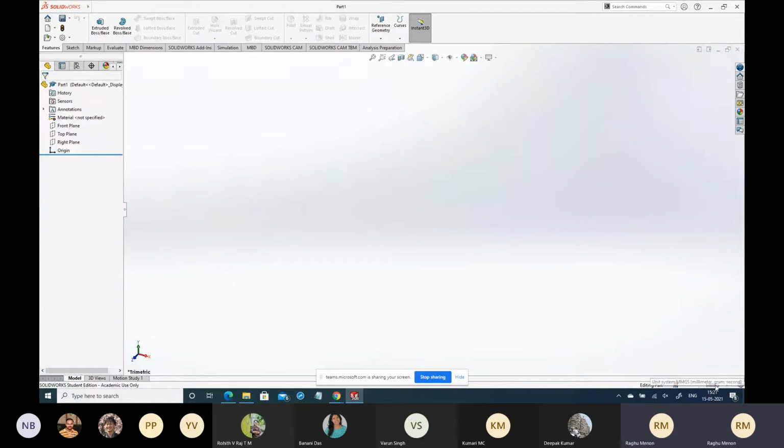It's millimeter gram second. You can also edit this and create a millimeter kg second. There is a meter kilogram second, which is the SI system, but this you cannot use because in regular practical design, the dimensions used are millimeters and not meters. Of course, millimeter gram second is available by default, but I know kgs would be a better unit. You can always create custom units if you want, but otherwise make sure that you're at least working with millimeter gram second units, because this is very, very important.